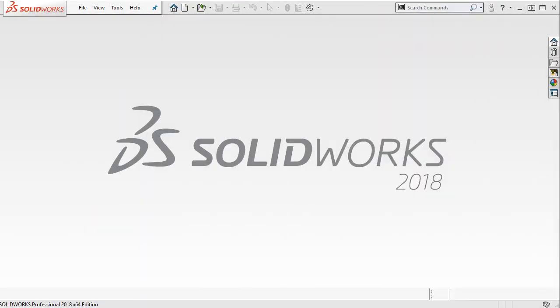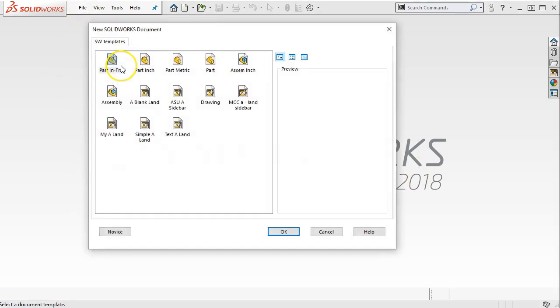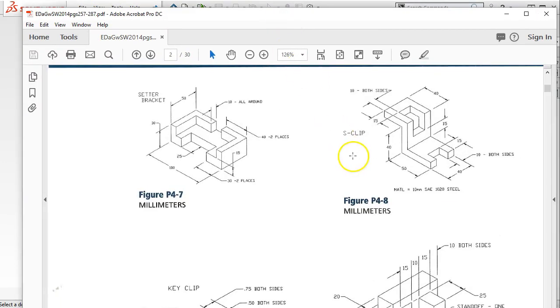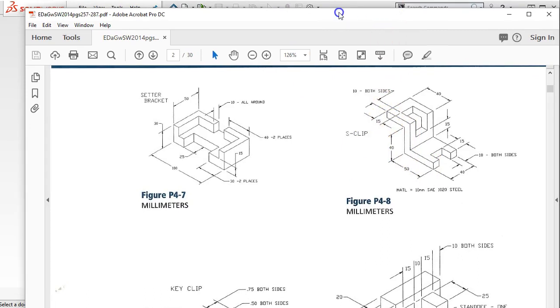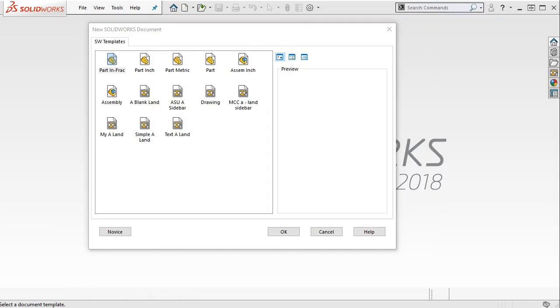Alright, so the issue here is if this is a sheet metal piece that is going to be bent, then we're not going to have square corners. We're going to have radiuses in there. So let's stay with the thin feature, and we'll treat it as such, but then we'll also take a look at what could potentially happen with the bend.